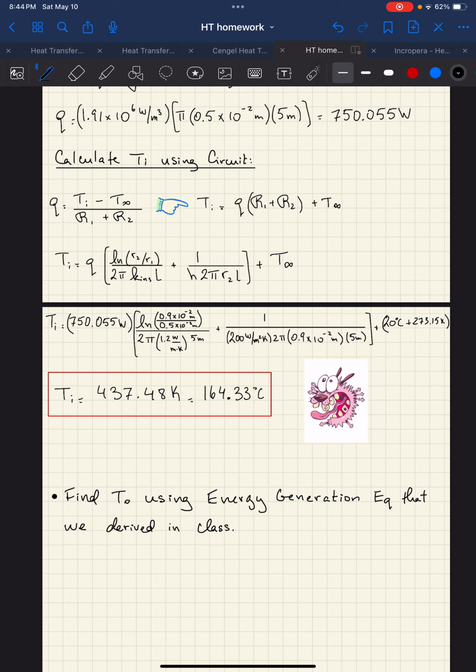So a couple things can be done. Either you switch out the power cables to bigger ones, where the heat transfer will be better and you'll have lower temperatures. That might be expensive. Another thing you can do is install some sort of cooling. So maybe you can put some fans or something, or maybe install the cables in some sort of oil or water to cool down the power cable. Additionally, you can also run less current through the power cable. So you have to basically reduce the current. That'll reduce the temperature of the power cable.